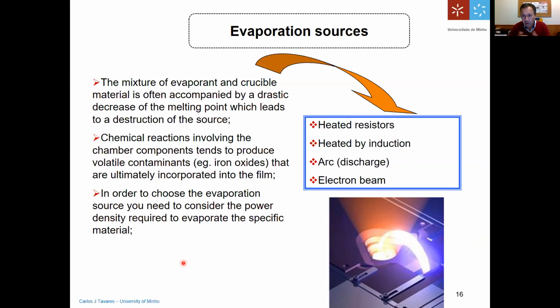Well, you have a magnetic field which fluctuates in time and induces a current in the bottom part of the pot or the pan. This current will circulate in a medium, which is a ferromagnetic material, which has a specific resistance. So the electrons which are moving around in this bottom part of the pan or the pot will release energy when they collide with the atoms of the ferromagnetic material.